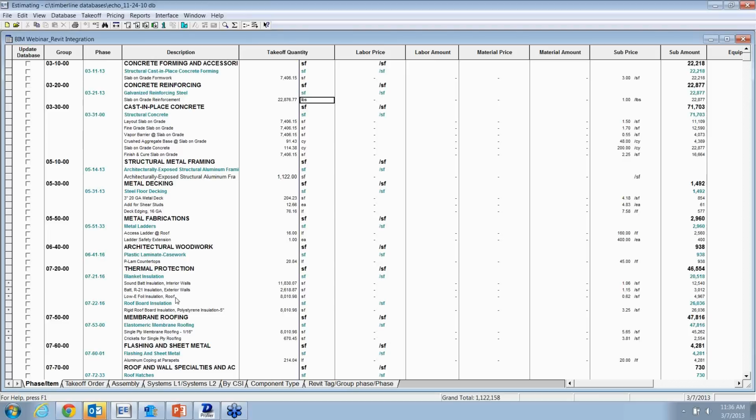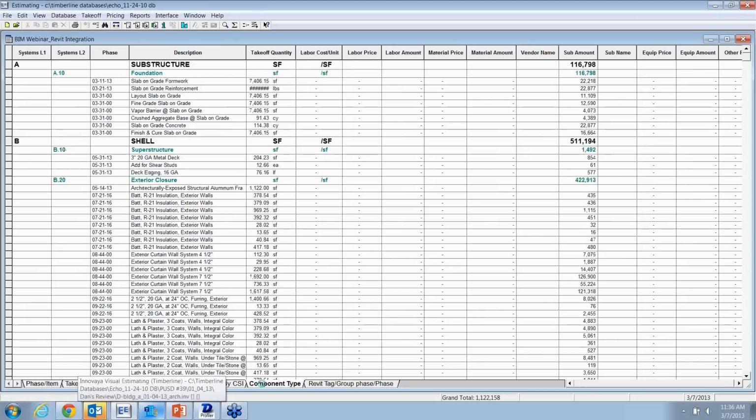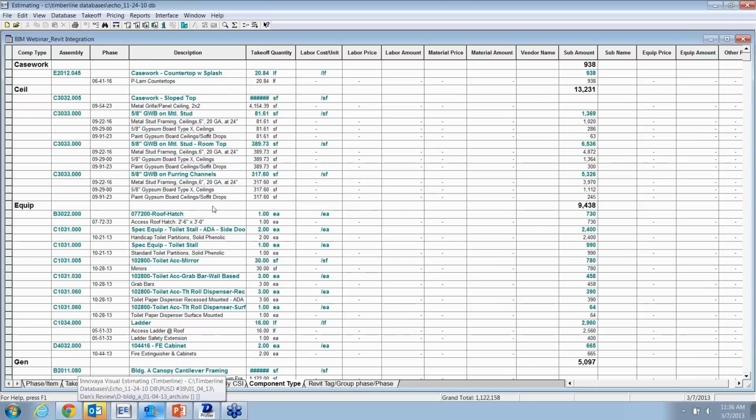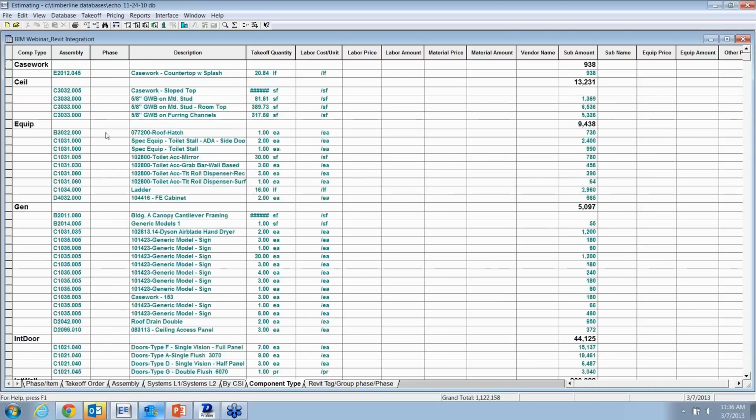quantities for that. But I also, using the WBS breakdown codes, kind of like I'm showing here, have different ways I can sort this. Like in this example, it is exactly how I've taken it off inside of BIM, and I can roll this up, but this could have easily been floor 1, 2, 3 all the way to floor 10. I've taken off the wall type once instead of having to do a takeoff on every floor for that. It just went and grabbed it.